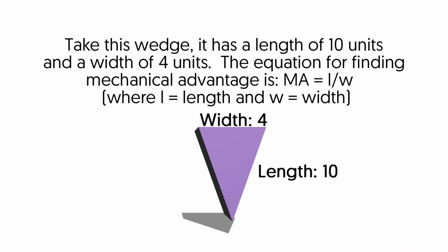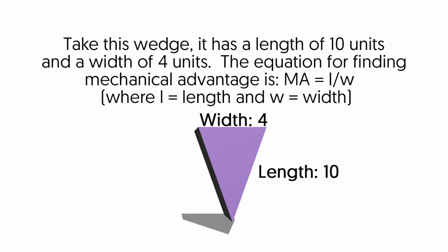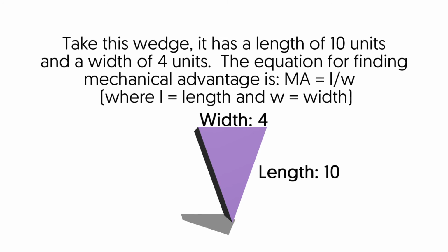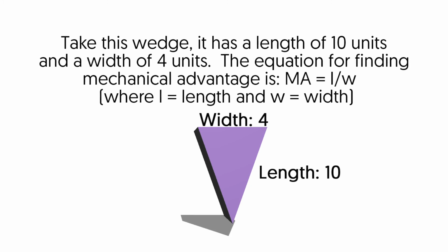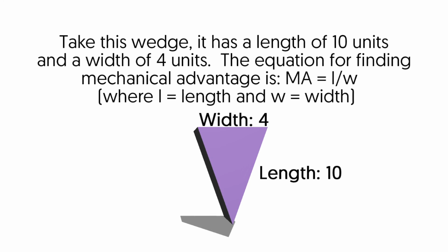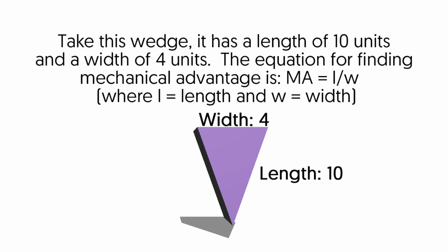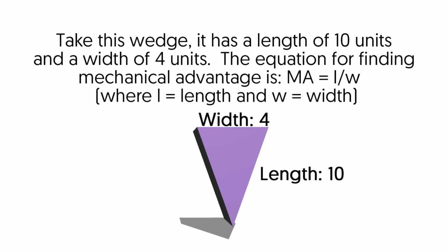Hi, welcome to this video tutorial about wedges. Now, wedges are one of the most common simple machines, as they don't have any moving parts but provide a large mechanical advantage. As you are aware, the shape of a wedge is just a triangle, usually isosceles, so that the length of two sides are equal, like the example shown here. Sometimes objects called inclined planes are also used to the same effect. Thankfully, finding the mechanical advantage of these two objects is relatively easy.